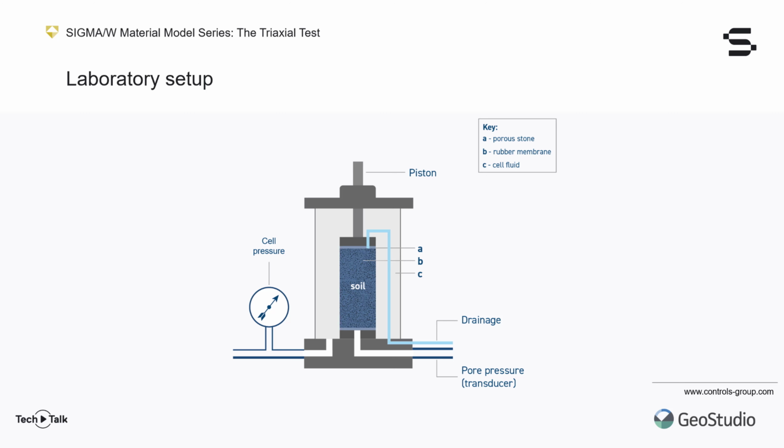strain. Another popular triaxial setup will instead feature a mechanical motor that will raise the entire bottom of the cell of the sample while the top cap remains fixed in space. Both setups achieve the same goal of compressing the sample. A conventional triaxial test is generally stopped once vertical strains reach 20%. This will of course vary depending on the materials tested and the level of stress.